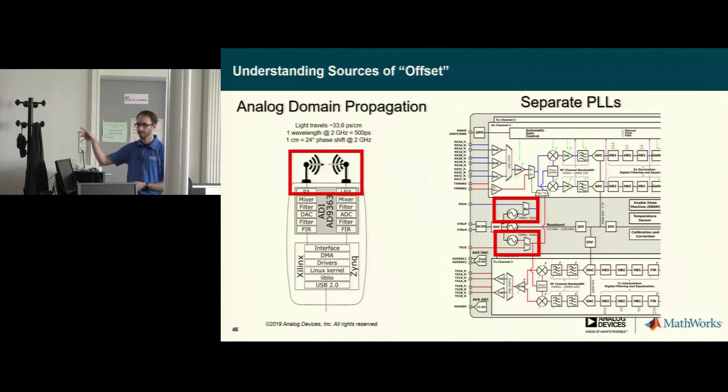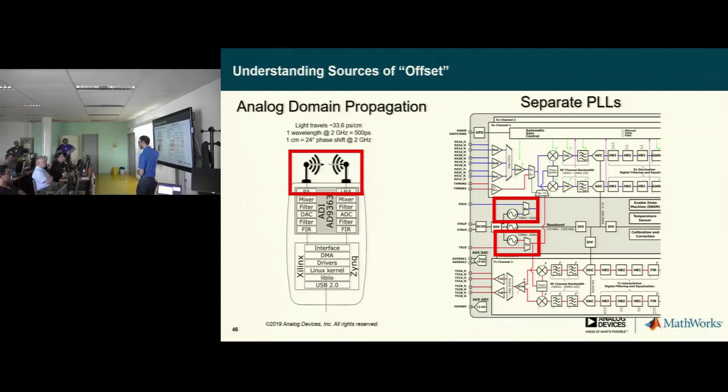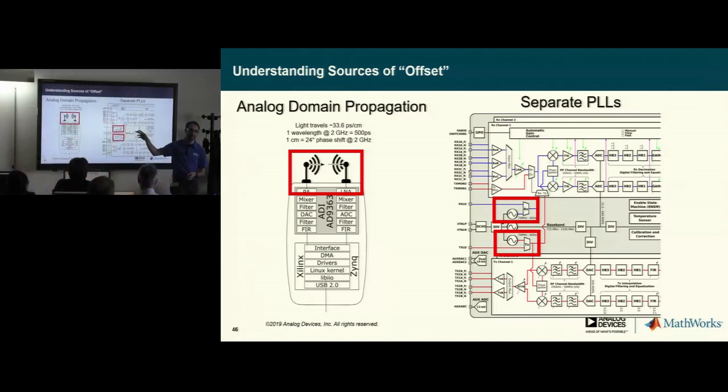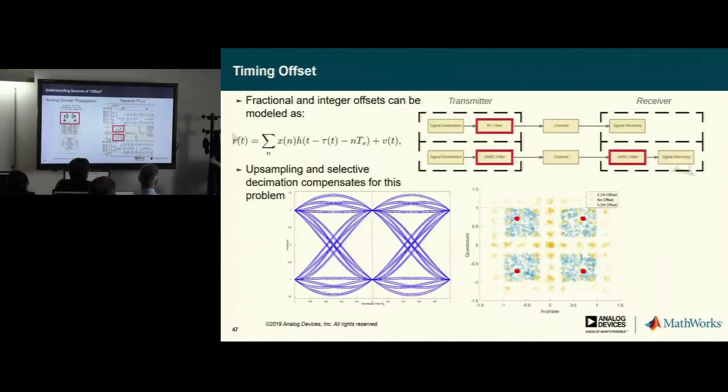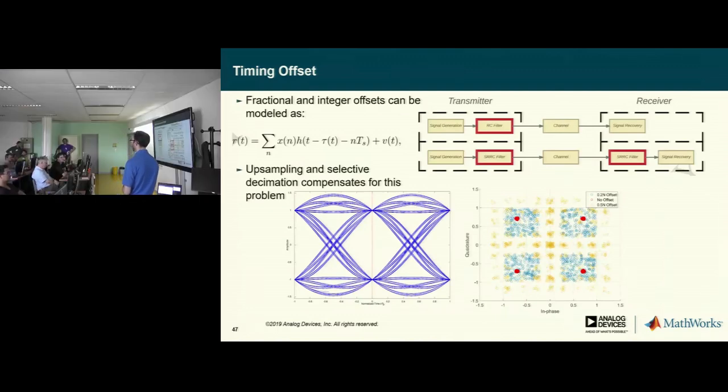So that means it's not possible to synchronize the phase comparators of both PLLs? No, not internally. So you could use the external LOs to help with that, but there's a divider that's not shown in this diagram, and that will cause a random 180 phase shift. And that is different every time you reboot the part.